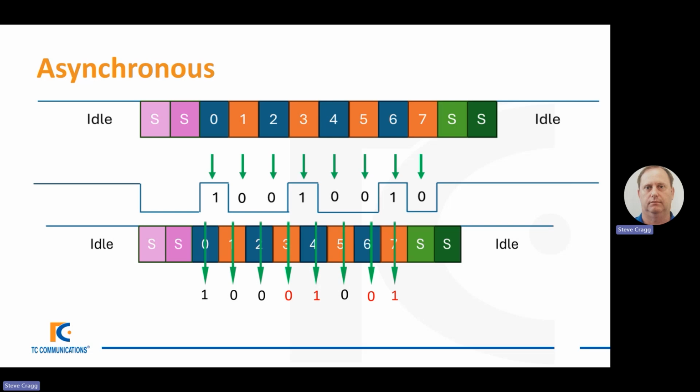Just to handle essentially overhead, and then you send 8 bits of data. So what you can see is, in that case, that effectively you are halving your data rate because you are using essentially overhead in terms of idle, start bits, and stop bits. So that makes it that, and the fact that both the transmitting and the receiving device are not totally synchronized means that it is typically limited to slower data rates.